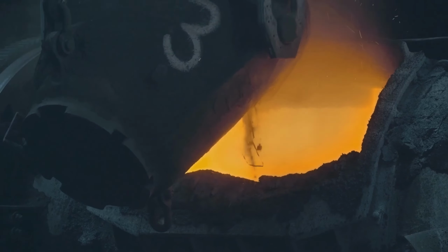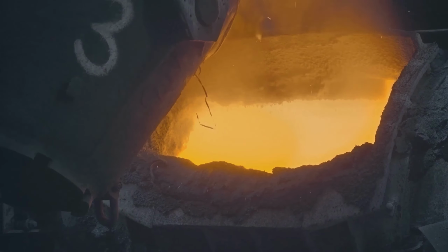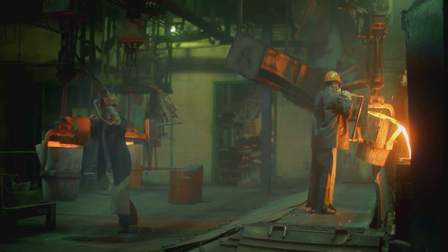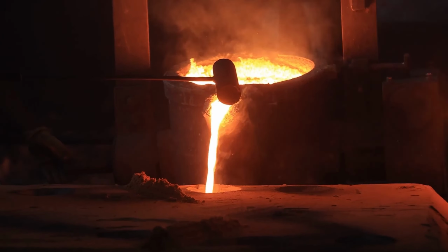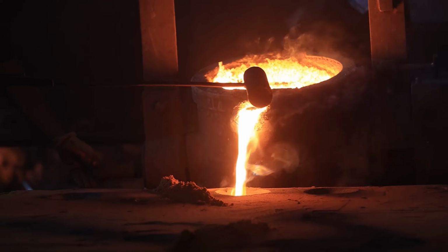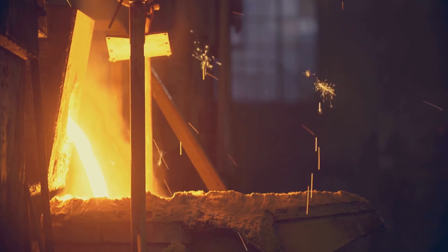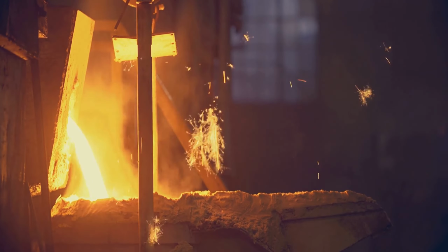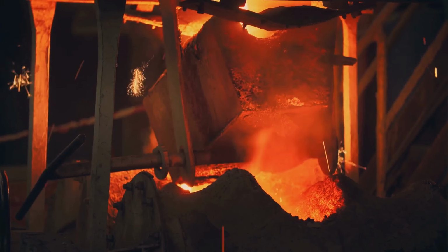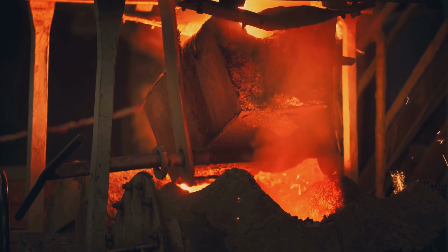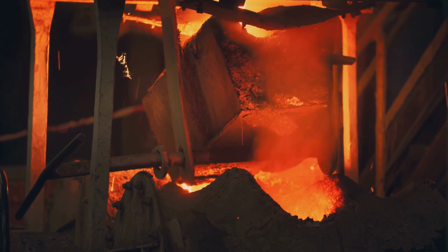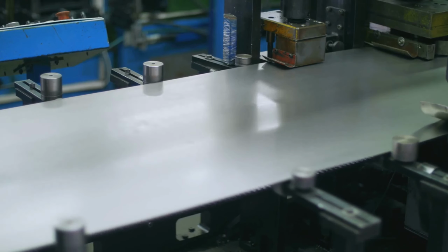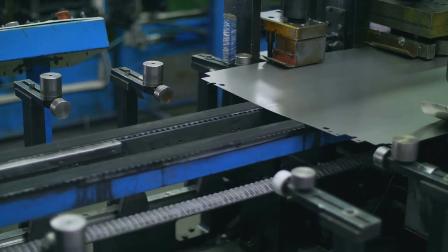In the context of electromagnetic stirring, or EMS, MHD is employed to stir the molten metal, promoting homogeneity and reducing microsegregation. MHD is also used in electromagnetic braking to control the speed of the molten metal, reducing surface turbulence and improving the surface quality of the cast product.